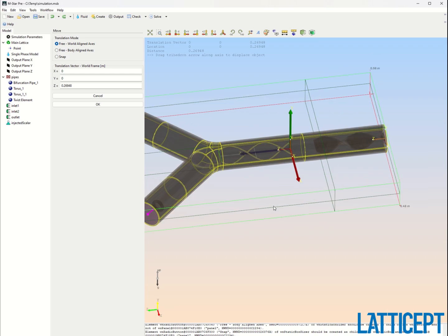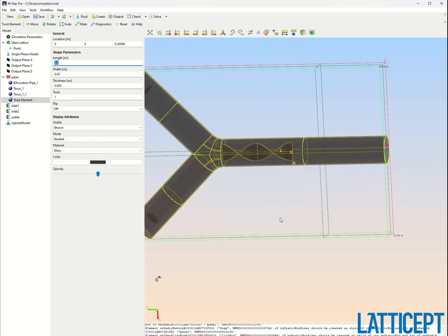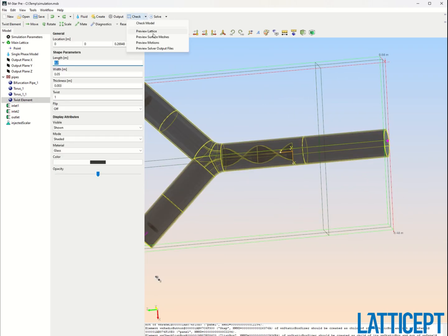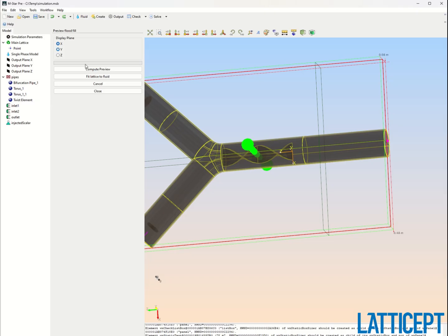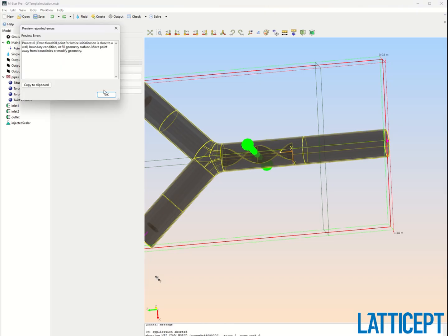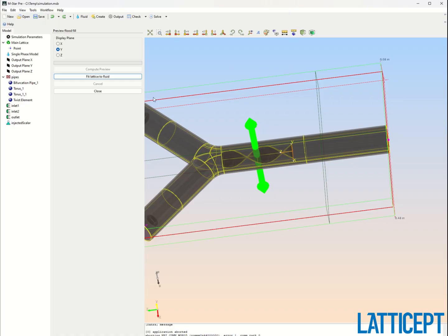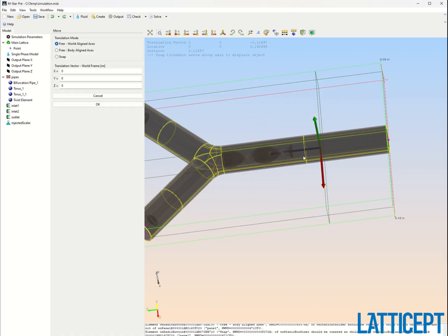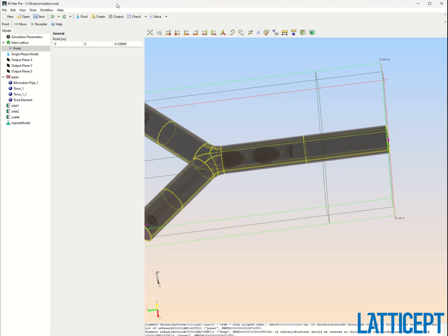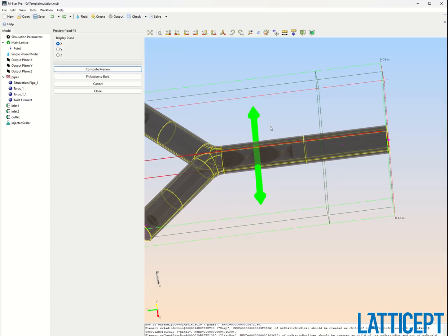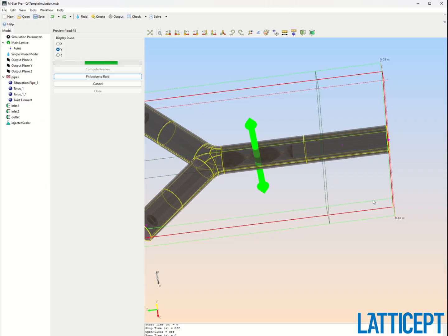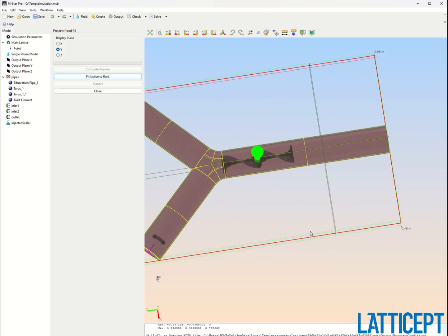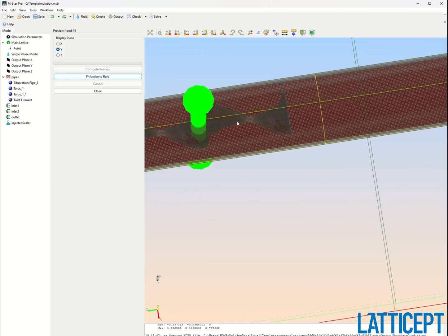All right. Now let's see what happens. Let's check our lattice real quick. We should see the lattice in the middle of it. Compute preview. Ah, see, I made a mistake. The fill point is now inside of that, so I need to move it. Move it down here. It's a volumetric fill point. There is no meshing, so to speak, but we do have to put it into free space. Now we should see, look at that. See, now it works. See how it's going around that?